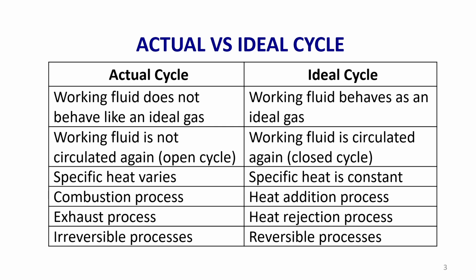So the working fluid is not circulated again, it is not reused again and again. That is what I mentioned in point number 2. The working fluid is not circulated again, it is like an open cycle, not a closed cycle. The working fluid does not follow a perfect thermodynamic cycle in this case. Whereas in an ideal cycle, which is the air standard cycle, the working fluid is circulated again, so it is like a closed cycle.